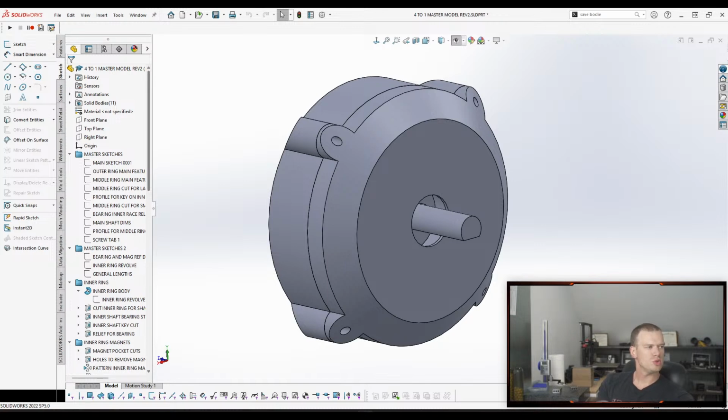No, you do share the skeleton. Well, you can share the skeleton sketch part file, but since it's one file, only one person can have it checked out at a time. I'm thinking, if you have a team of engineers and you're trying to distribute information between them, but you have to keep that revision control, only one person is going to be modifying that file anyways. And you have to be careful because as they modify it, that's going to push updates to all those other parts that are being built off of that.